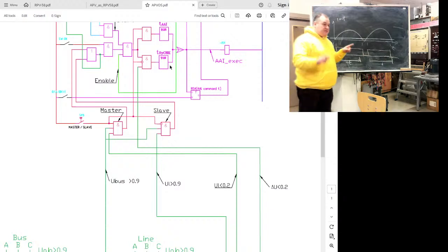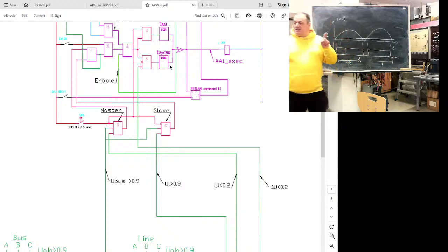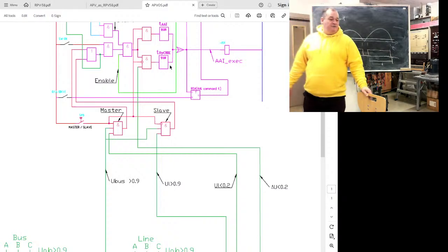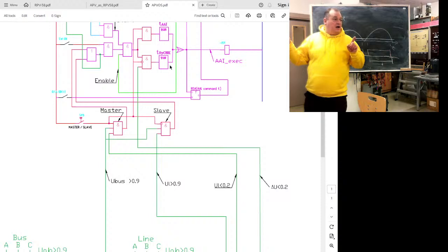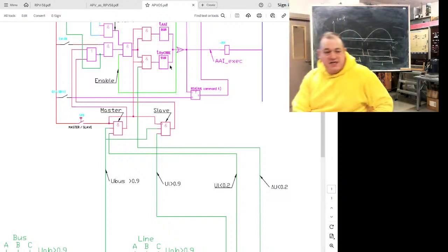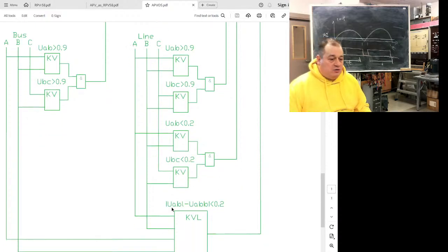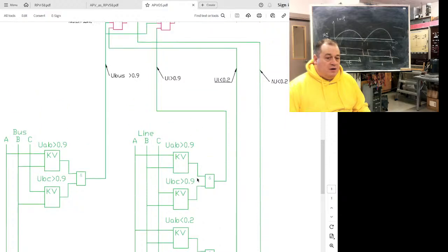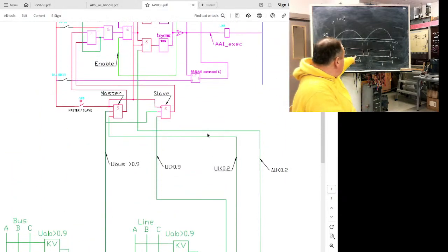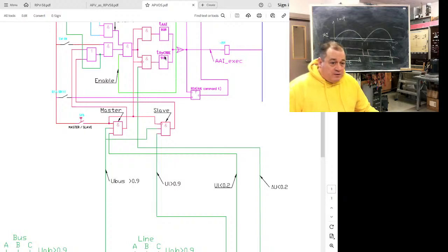It could be simple, with two frequency relays, but it isn't easy to measure frequency precisely without a long period, and we don't have a long time. So synchro check, or check for slide, is done with the help of a differential voltage circuit and comparison of its output signal with the predefined time of this timer. If longer, it will operate. If shorter, it will lock.